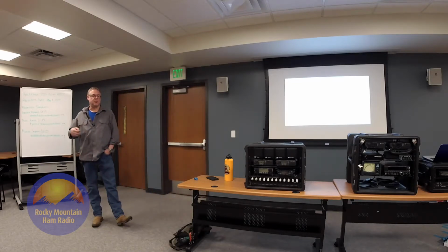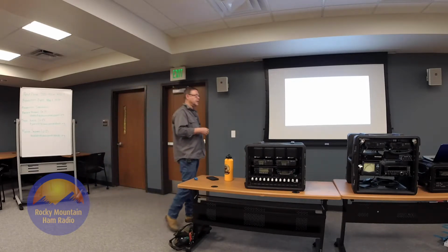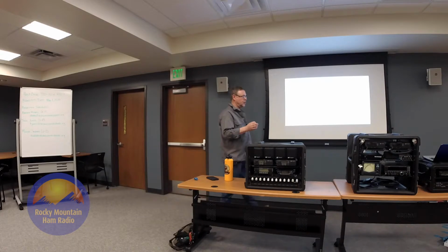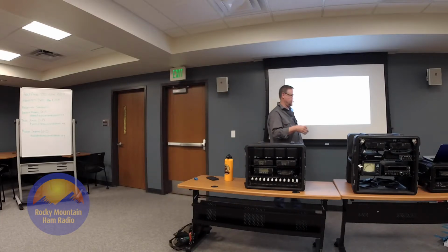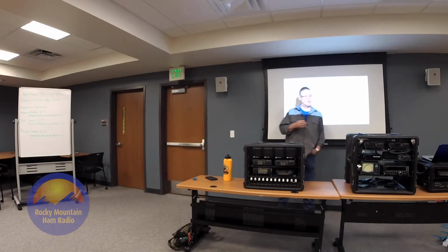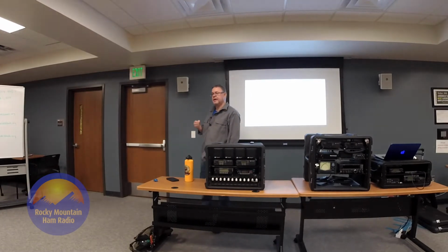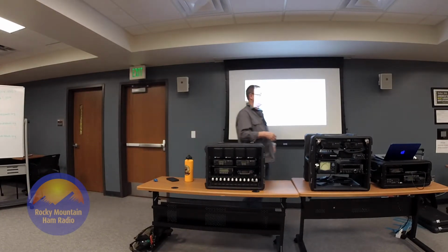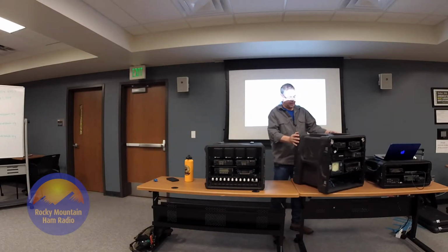You don't want your wire to be your weakest link just because you're being cheap and this is what you had in your box. And so you grabbed it and used it and you ended up using 16 gauge for 100 watts. It'll get warm. It'll choke off your power to your radio. So keep that in mind. Short runs, however, managed runs. If you have to add a little bit of extra wire inside to manage it, do it.